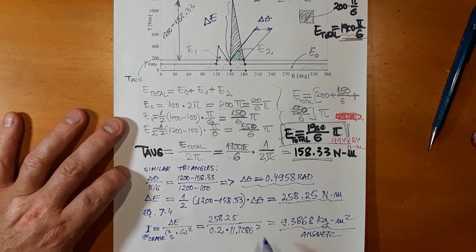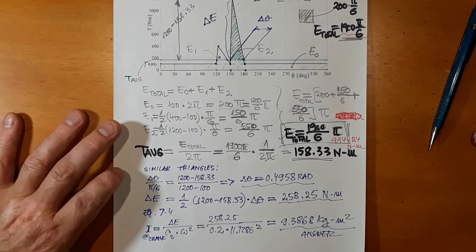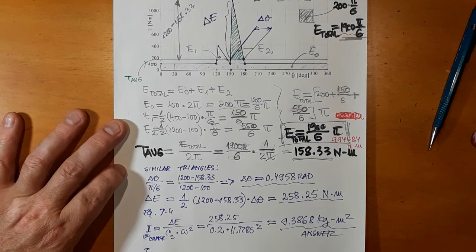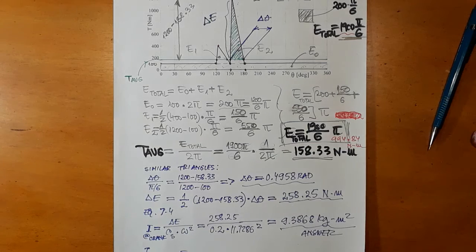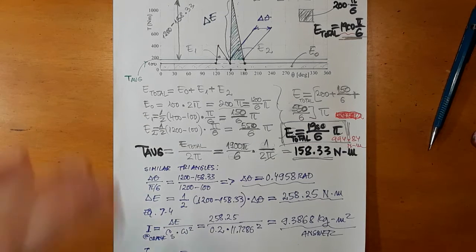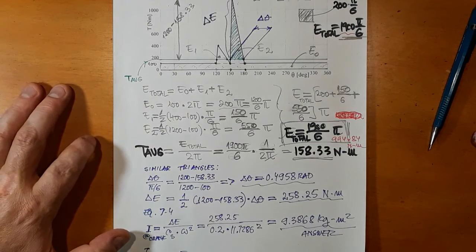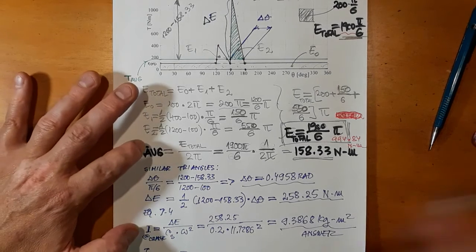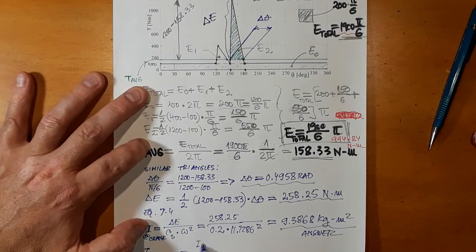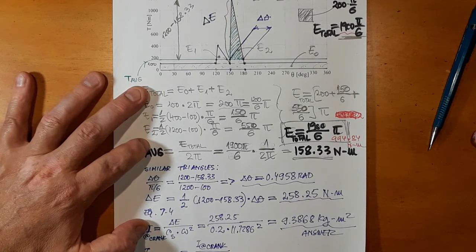Okay, so what is the moment of inertia at motor shaft? This is the equation that is in the notes. It's equation either 3.9 or 4.3. So it's I at crank divided by transmission ratio squared.